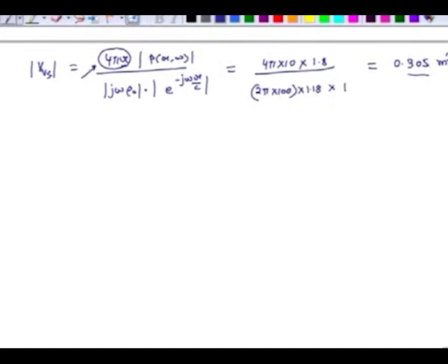What will also simultaneously happen is a change in pressure, because as I move away from the source, even though the radius is increasing, the pressure or the SPL generated by this particular wave decreases rapidly. So, even though this term increases, this particular term decreases as r increases. So, the value of the volume velocity reflects the position of the point of observation and also the pressure at that particular point of observation.